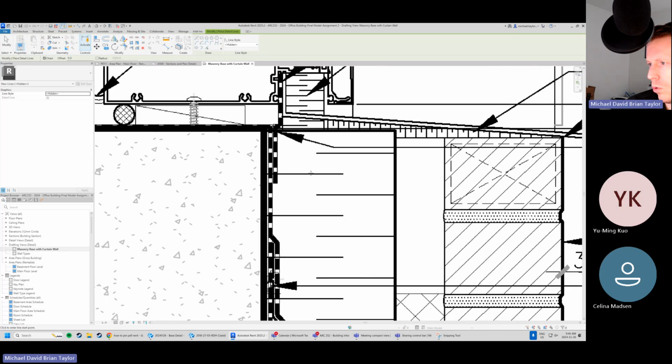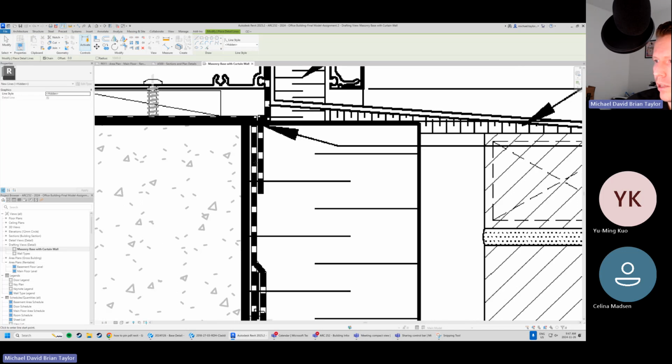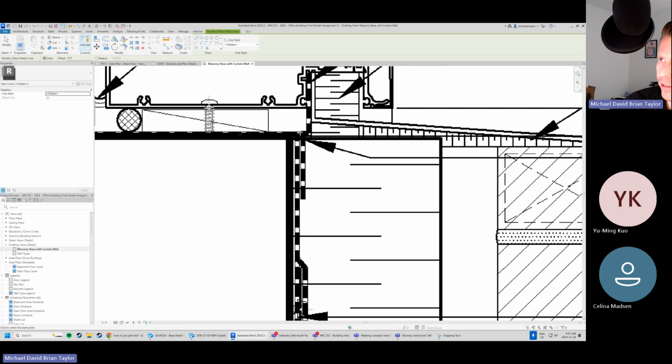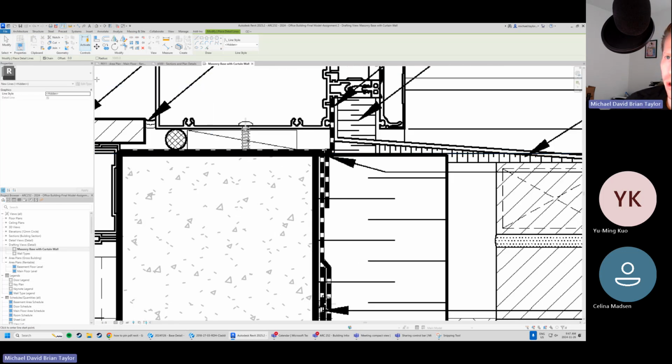So this is how, when I was working in AutoCAD, I would draw a membrane: a really thick dashed line with two lines on either side, right? So we're drawing it like these really heavy dash dot style of lines. So what I can do to start us off here is I'm actually going to offset by 5 mm. So I'm going to jump here, 5 mm.